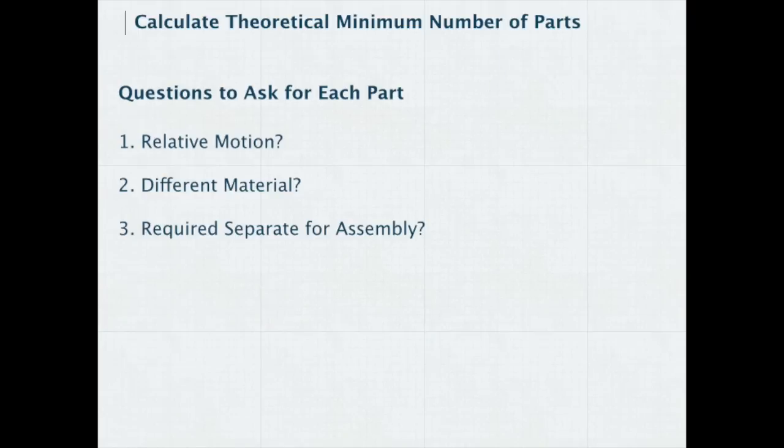We'll do this in two parts. First, I'll talk about calculating your assembly index of efficiency, which is just a good benchmark that you can use to really track how your design matures over time. The actual number doesn't really matter, but it's just, are we going in the right direction or the wrong direction? And then we'll dive into the specifics of picking out materials and processes.